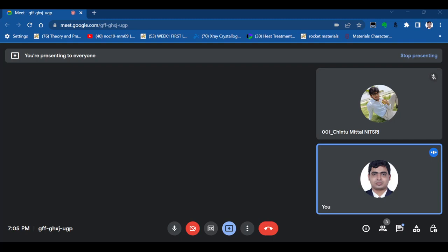From this we get the relation that sigma 0 is equal to 2k. What is this k? This k is basically our tau max. So that's why I use this equation by 2. When this 2 goes to the other side, this becomes our yield stress.